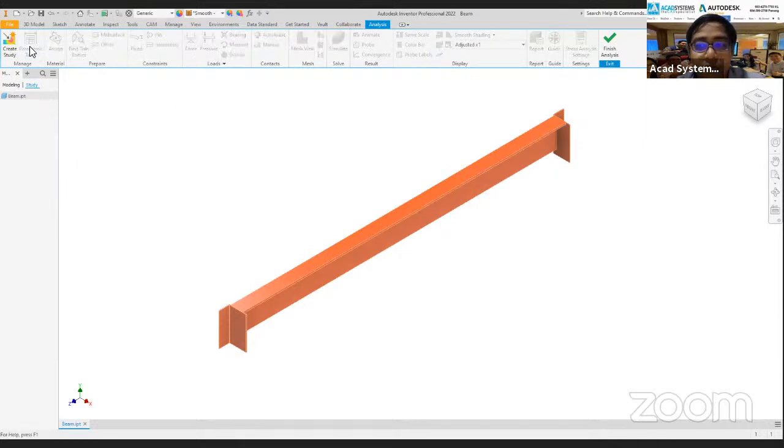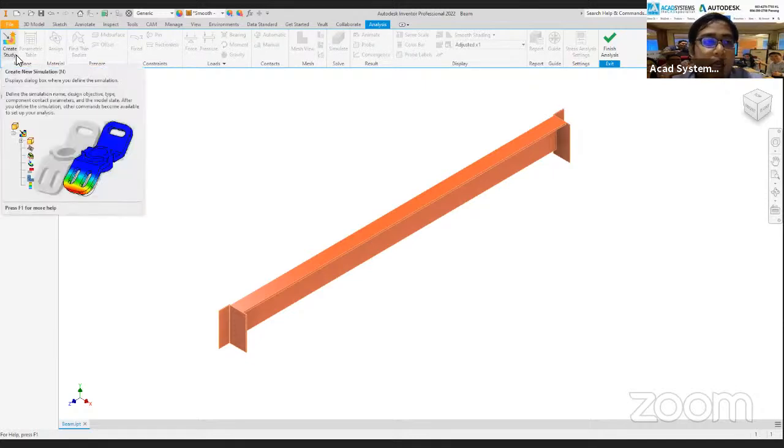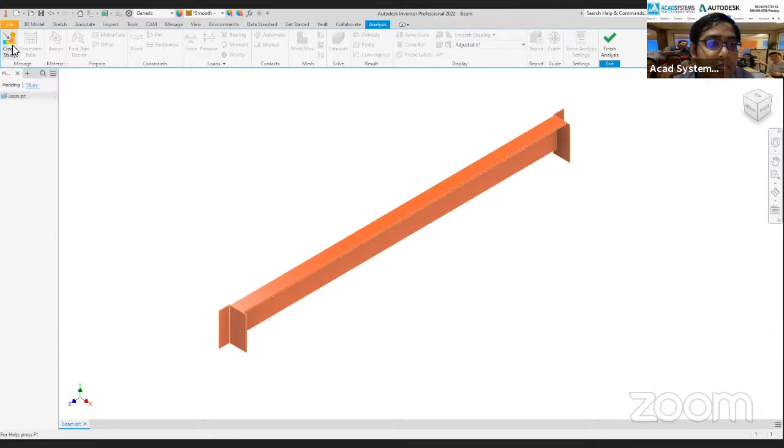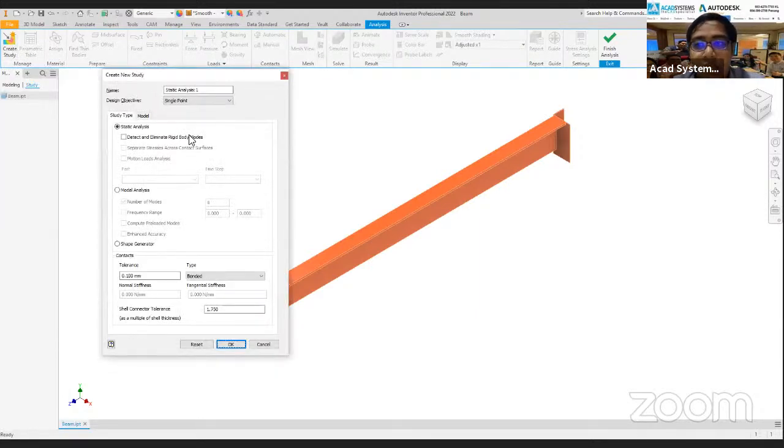When you start, most likely you will have these empty things that you cannot select, except for the case studies. To start with the stress analysis, you go into these case studies and select which studies you want to create, whether it's the static analysis or the modal analysis. First of all, I will show you the static analysis. Over here we also have this checkbox for the eliminate rigid body modes, which I will show you later on. So we start first with this static analysis.